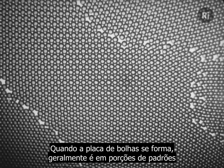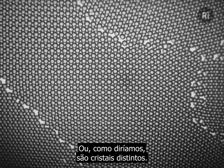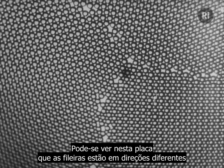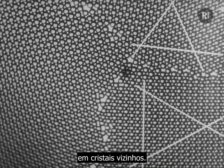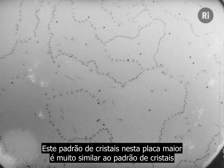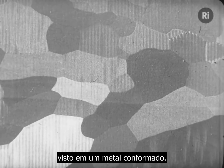When the raft of bubbles forms, it's generally in portions of pattern which are not parallel, or, as we should say, are distinct crystals. These meet at crystal boundaries. It can be seen in this raft that the rows are in different directions in neighboring crystals. This pattern of crystals in this larger raft is very similar to the pattern of crystals seen in an etched metal.